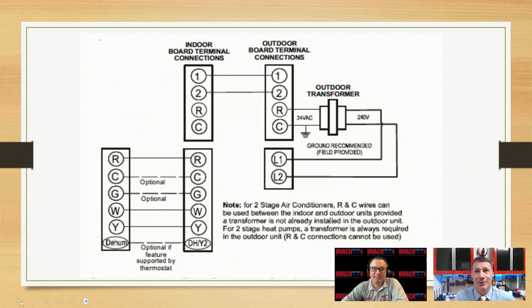The same way we do the rest of them. On the T87 or thermostat side, what are you supposed to have? 24 volts. On the communicating side, whatever the parameters are by the manufacturer. That's right. So with theirs, typically, if it's a gas furnace, 2.2, 2.8 with a 0.6 volt DC bias between the two of them. And it shows you exactly on that outdoor unit where our 24-volt common is grounded to our chassis.